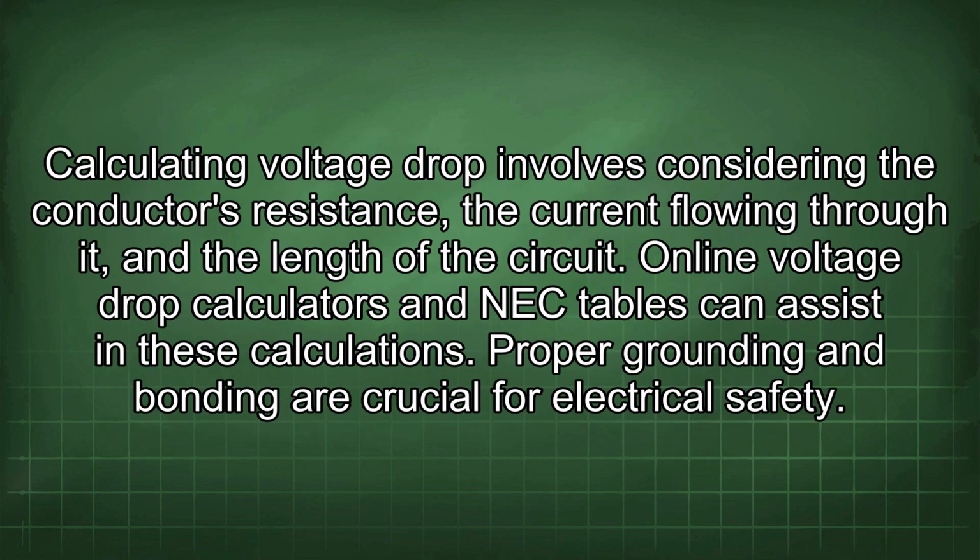Calculating voltage drop involves considering the conductor's resistance, the current flowing through it, and the length of the circuit. Online voltage drop calculators and NEC tables can assist in these calculations. Proper grounding and bonding are crucial for electrical safety.